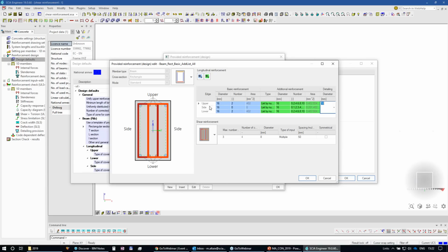As you can see, in the template, I define the top reinforcement as 2 bars. So this is number 1 and this is number 2. But SCIA automatically adds gray bars for me. The diameter is 10 because those are detailing bars. There is something really important I would like you to keep in mind. Those gray bars will not be used for the calculation of the capacity of the cross section.